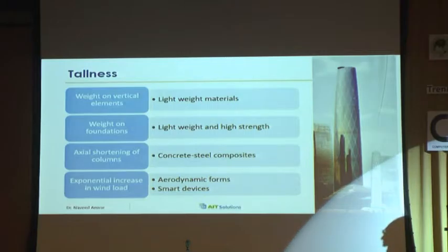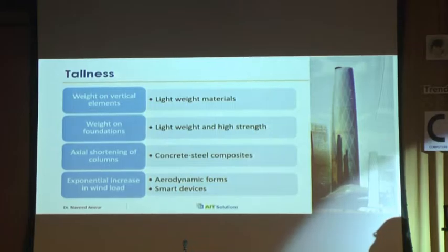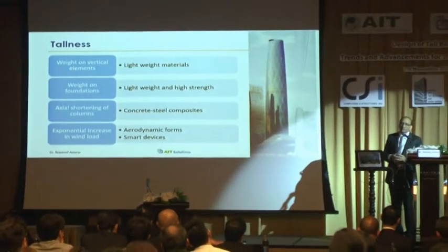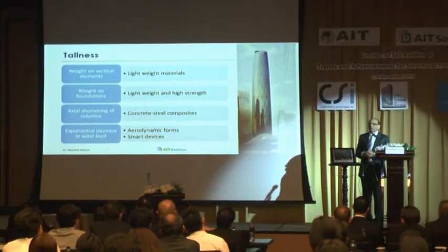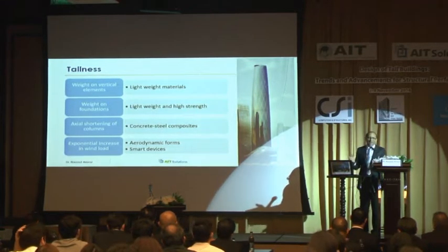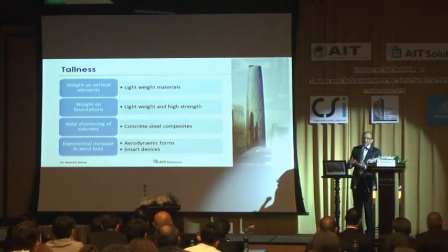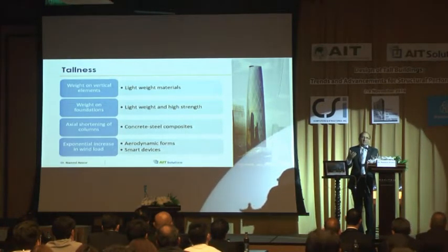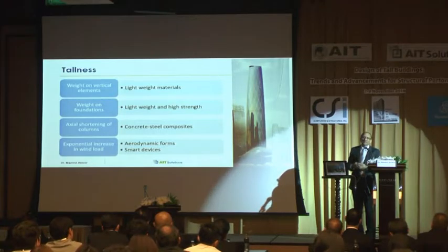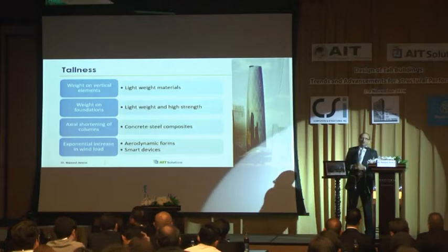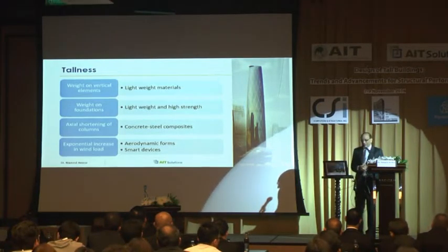But obviously, nobody needs a column that doesn't carry any load. You need a column that carries a load. So the column must carry, at least, 70%, or 100%, 200%, four times more load than its own weight. Then we talk about different materials and so on. So the self-weight, the simple gravity weight because of the density itself, will become a challenge. And the solution is of course lightweight materials and also high-strength materials.